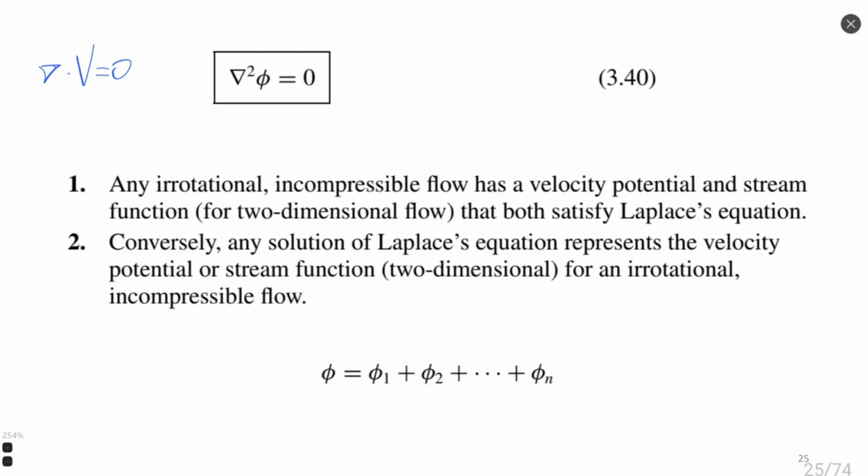So what we will do, we will elaborate simple flows. We will call them elementary flows, and Anderson also calls them elementary flows. And combining elementary flows, we obtain more complex flows. For example, flow over a cylinder, irrotational cylinder or rotating cylinder, flow over a sphere. And then we will see how to create a numerical method to calculate flow around a complete airfoil based on this Laplace equation.